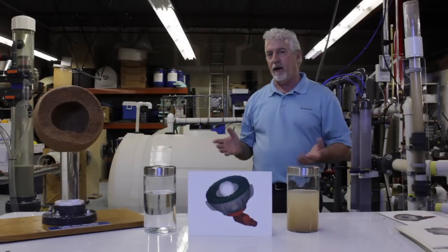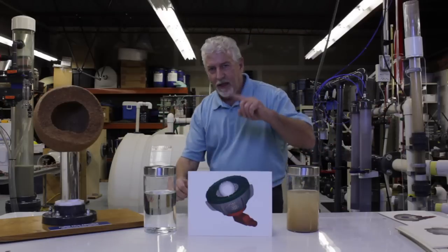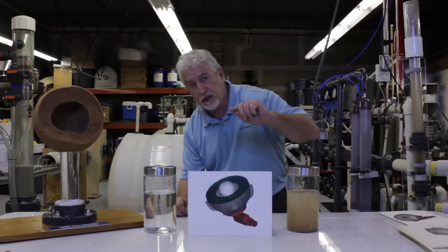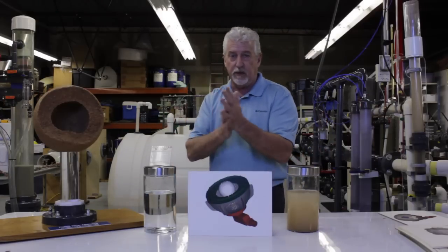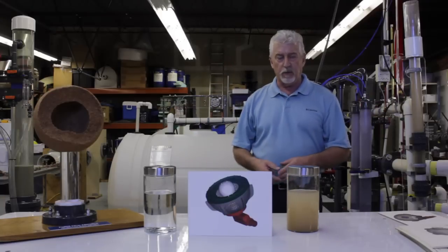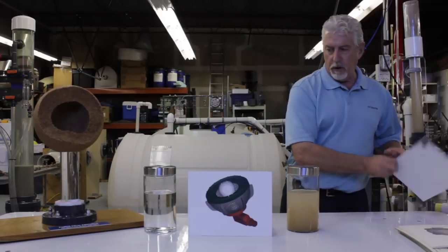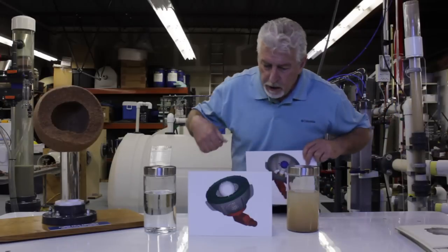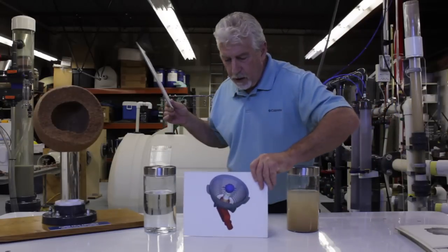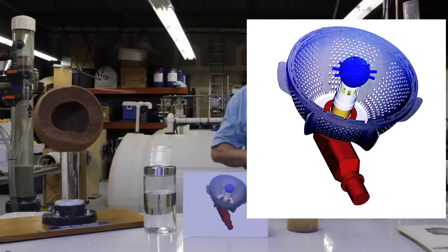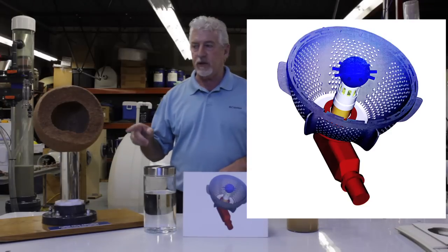The inefficiency of backwash I showed you was sand. That slow, lethargic, half inch per second velocity that's supposed to clean the grains. You couldn't wash your car with water going that slow. What do we do about it? Inside the inner drain, we have our backwash jets. We have a Gatling gun of spa jets delivering water in the backwash cycle.